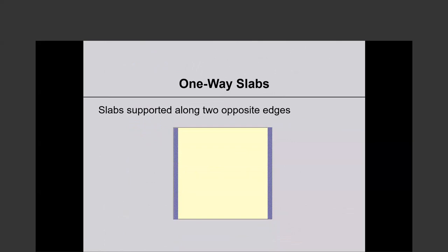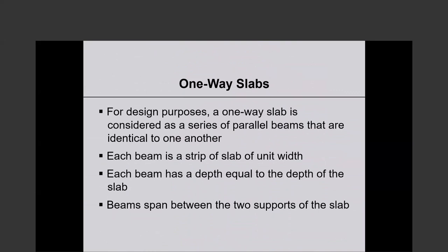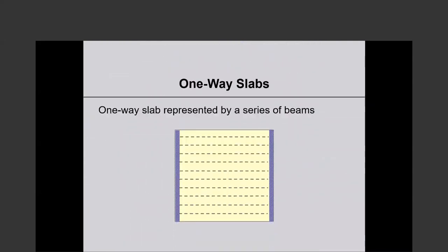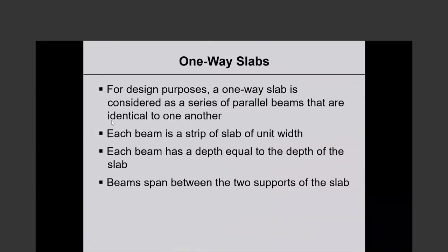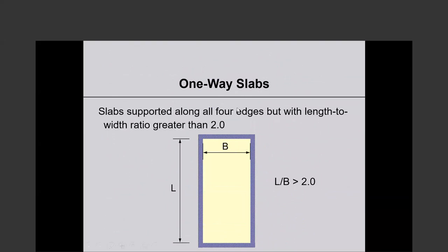Now I have a one-way slab, and I am thinking that time is out, and this is easy material. I think all I need to point out is, let me say a couple of things. So if you have a beam supported slab, beams on four sides, this slab will bend in both directions, in the short direction and the long direction.